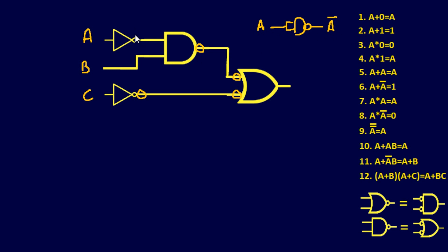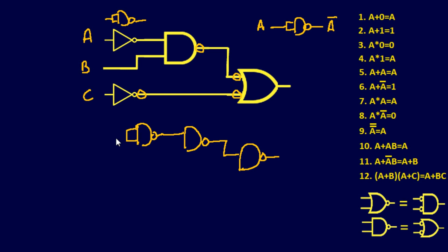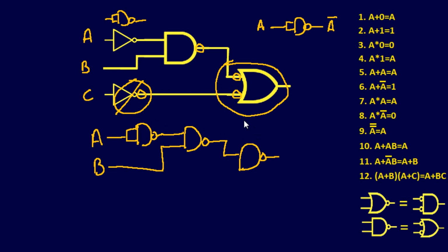So another method I can do here is add a single NAND gate. So let's go ahead and redraw this all in our NAND gates, because again, our NOT OR down here is a NAND gate, there's a NAND gate, and shorting the inputs on a NAND gate will create an inverter. So this would look similar to, let's see if I can actually draw somewhat decent today. There's one input, and that we got to account for that NOT, and we're going to short the 2 inputs together. So that's A, there's B, and again, as we looked at earlier, this particular part is one NAND, and this gets completely negated.